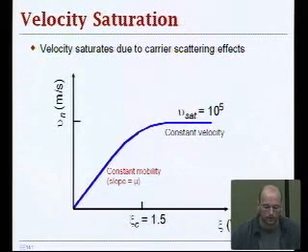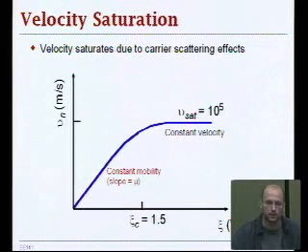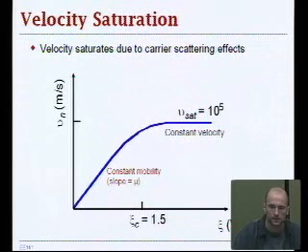That's a good question. The minimum feature size has scaled down, and the voltage has scaled down. So basically the voltage has been scaling down at a slightly reduced rate than it was in the past. The feature size has been scaling at a faster rate, such that when you apply a voltage over your drain and source terminals, you have excessive electric field.